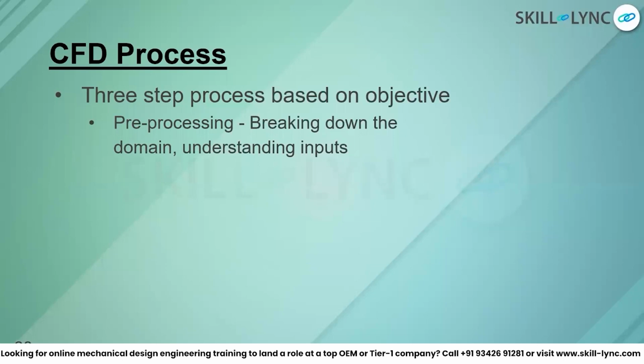So before using any tool, these are the things I'm telling you. These don't require any tool. The tool is just for the input. The pre-processing part is that you understand the domain and what kind of physics you're going to solve. When you have a CAD, understand whether the CAD is proper. Does the geometry have any flaws, missing surfaces, other issues or sharp edges?